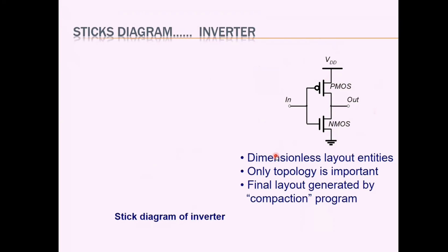The stick diagram does not have any dimensions. Maybe the ratios can be indicated near the transistors. Only the interconnection is important. That is, the topology is important, and the final layout can be generated by a compaction program.